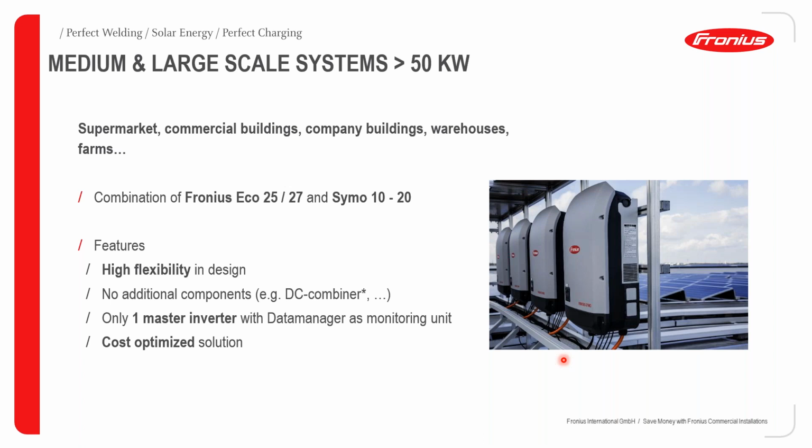The features of these inverters include a high flexibility in design, no additional components needed as in the case of a DC combiner. So in a case where you're using a centralized system, of course, you don't need a DC combiner. You can just connect all your systems directly. We have the possibility of using only one master inverter for several systems as connected on the Solar.net.